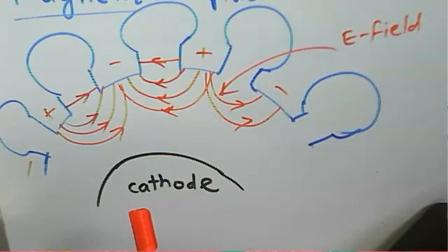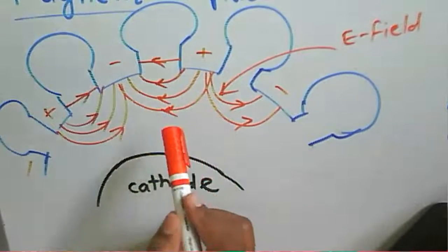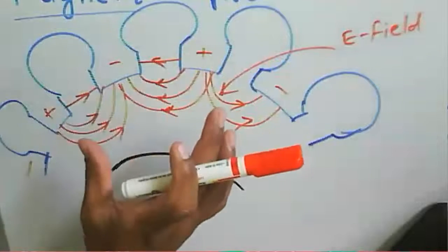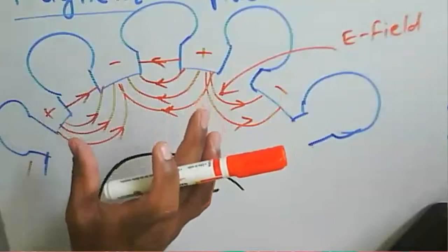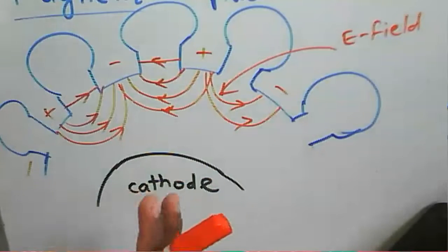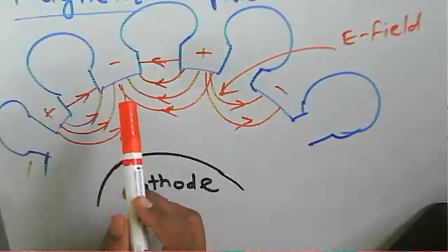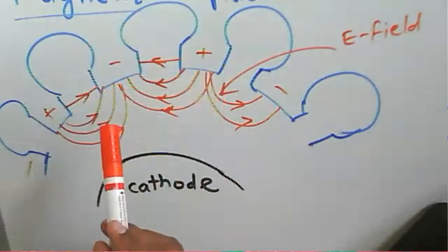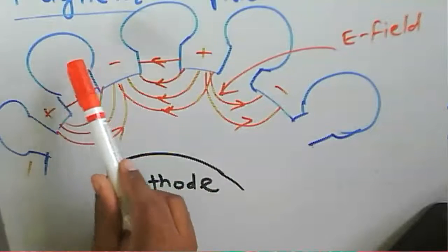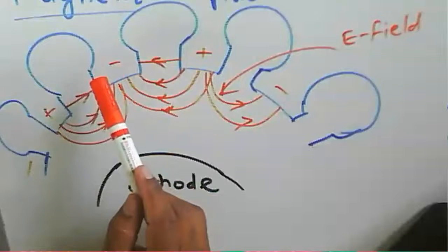If the phase between alternating cavities is not pi, then the operation of this magnetron will not be highly efficient. That's why we need to consider the various magnetron tubes. The modes of operation of the magnetron depend upon the phase of these alternating cavities.